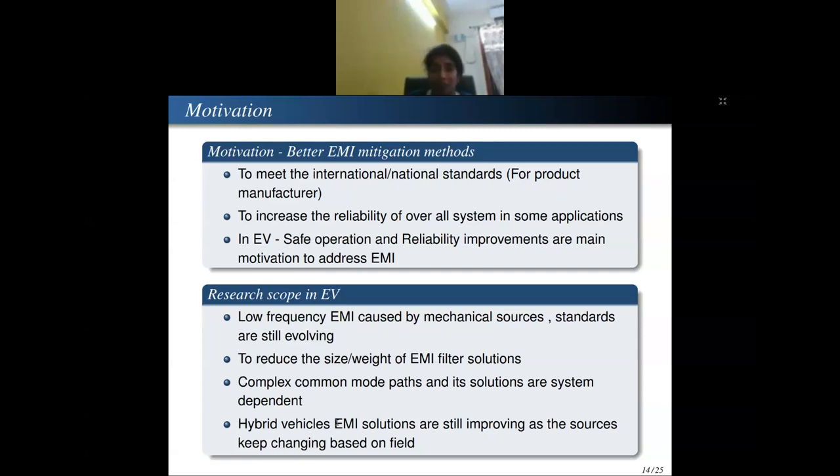Why? See, you have a switch. Inductance matters because whenever a switching action happens, the inductor has a nature of opposing the sudden change in current. So whenever you open or close the switch, first you close the switch, the inductor will store the energy. When you try to open it, even that parasitic inductance will try to impose and produce a high voltage across the switch. That is your peak overshoot, right? So if the peak overshoot is increased, automatically your current through the capacitances will increase.